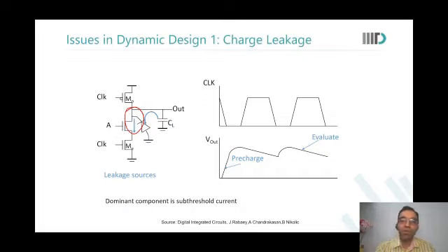It is based on that overall evaluation time of that combinational block, na? Yes, sir. So if you need some period, then you need that period. Are you able to see this? So that is constrained. It would depend upon the critical input as well, right? The input which is most delayed. Yes. So there will be lots of signals which are coming to your combinational logic, and the last one, and how much time it takes to evaluate that one, that will finally determine how much you need.